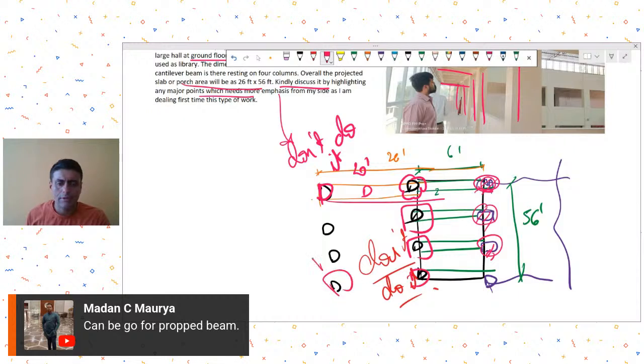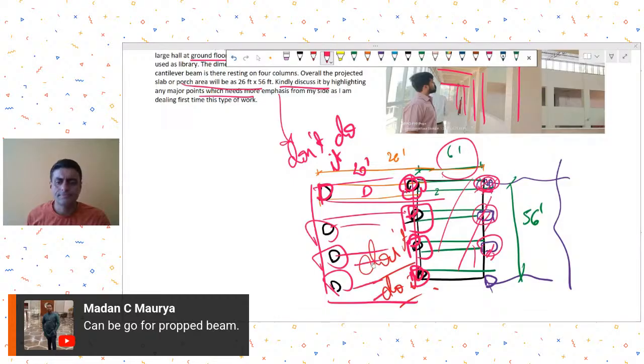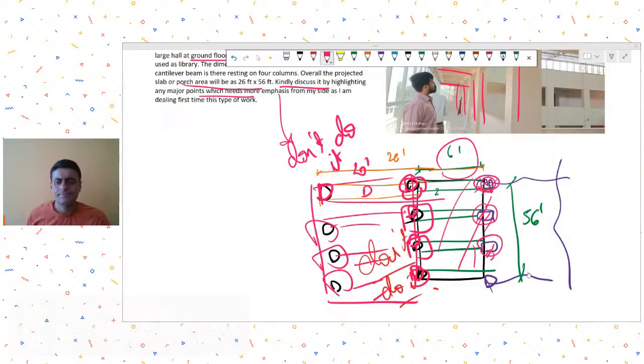I will suggest you not to stress the old structure, which has a 6 feet cantilever. Leave it as it is. Create a new system over here, separate like this. Have 20 feet spacing columns and create a new framing over here. Right? Okay.